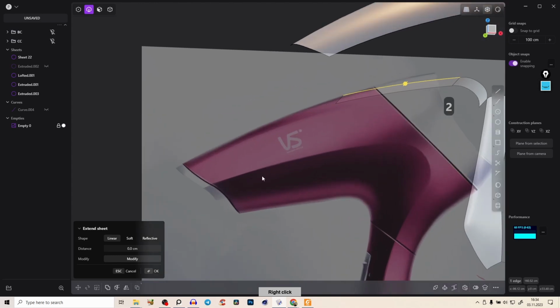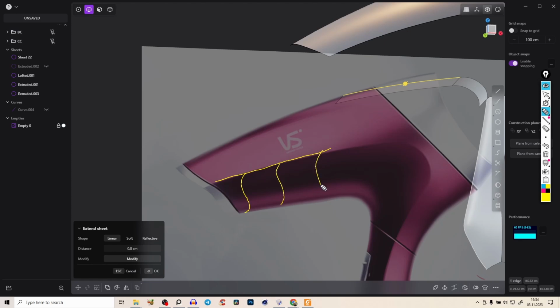Before we start to connect this centerpiece, which is curved, let's first focus on this thing. Because if you see, here it's bright and here it's dark. That means that this shape, here we have the edge, this shape is going like that, right? So something like that. Here again, we have G1 or G2 as you want. And here obviously G0 because we have a sharp edge, but we want a nice curved surface like that.